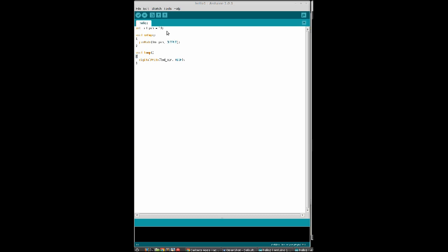The Arduino has a couple of predefined functions that almost every program will make use of. The first is setup, and is called when the Arduino is first started, either when it powers on, is reset, or a program is uploaded. In this function, I'm using the pinMode function to let the Arduino know that I intend to use the LED pin for output.